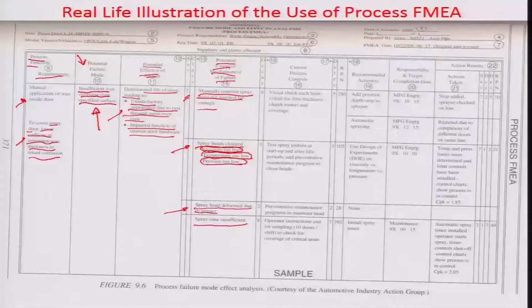So sometimes, because of the untrained operator and because of his inability to go on in flow with the production process, he might find time between many vehicles which are coming sequentially to be insufficient to coat the whole vehicle with a certain wax layer. On one hand, the line is balanced for a skilled operator, and if you put an unskilled operator, these problems are going to happen. So the quality engineer again tries to decide on the occurrence levels which lead to this failure mode of the various mechanisms.